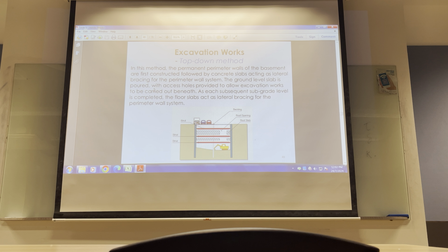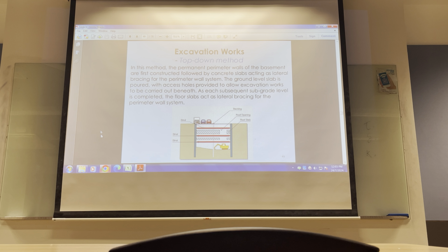But doing top down requires you to have king post, and you need to devise or sequence carefully, allow sufficient time for your downward construction, because excavating downwards in a top-down manner takes longer time and more effort.